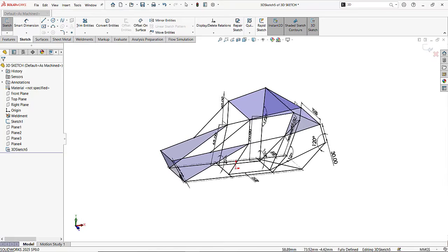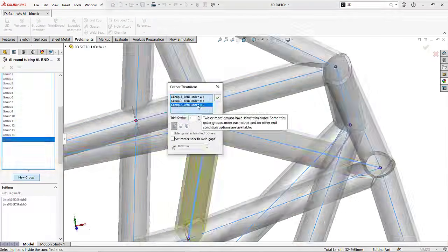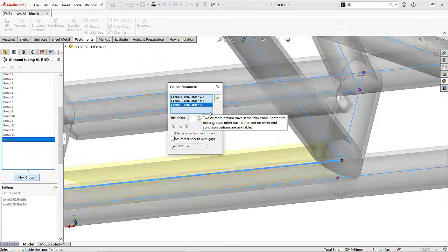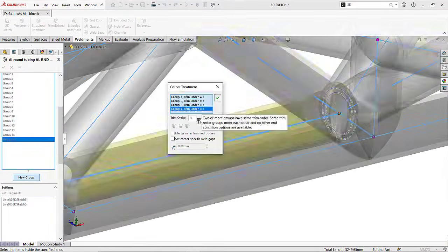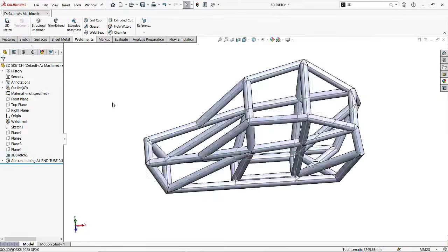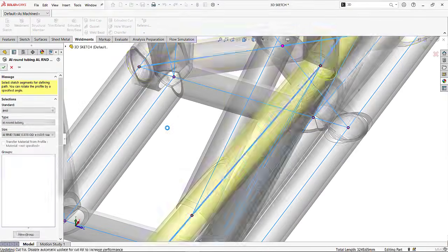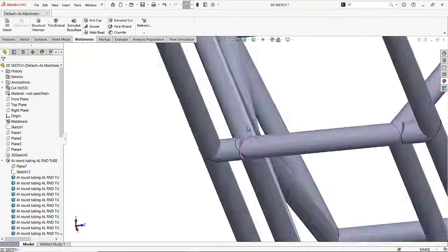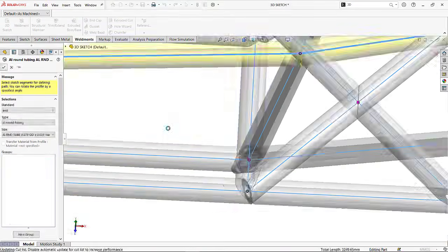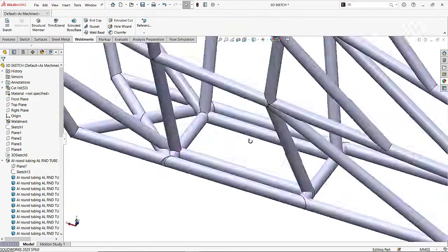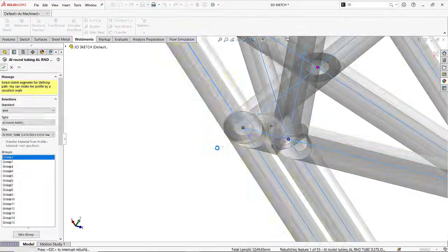And once the chassis skeleton is ready, we will move to the weldment features to give it a realistic frame look with the structural members. So if you have ever wanted to design a custom frame, roll cage or any tubular structure in SolidWorks, this video is going to make everything super clear. Now let's jump right in and start building our buggy chassis using 3D sketches.